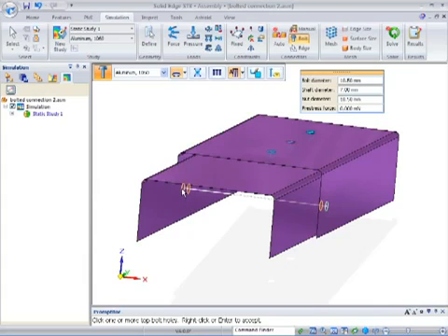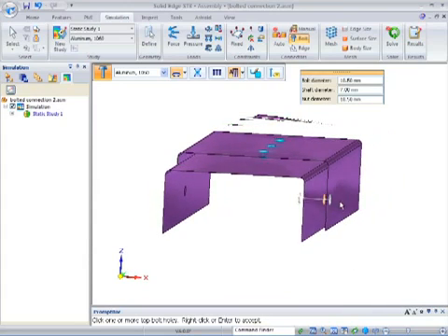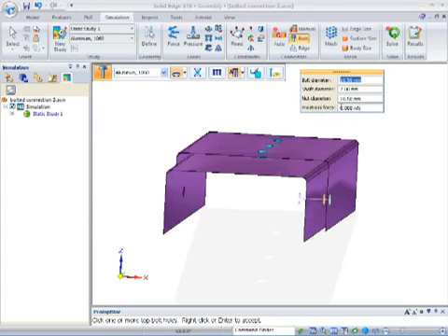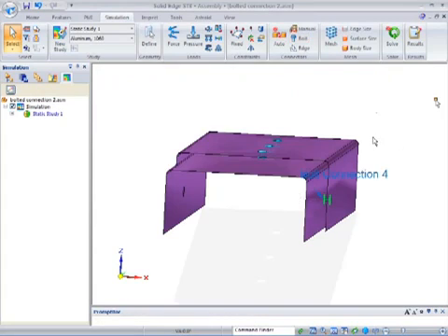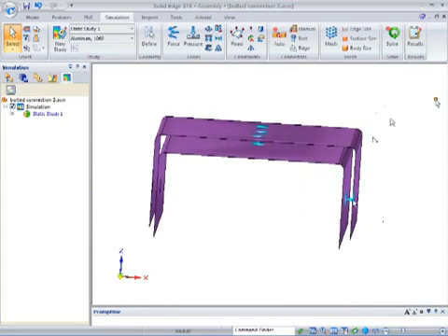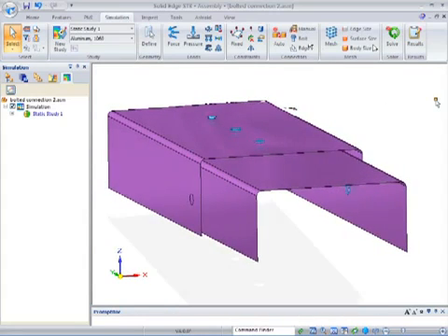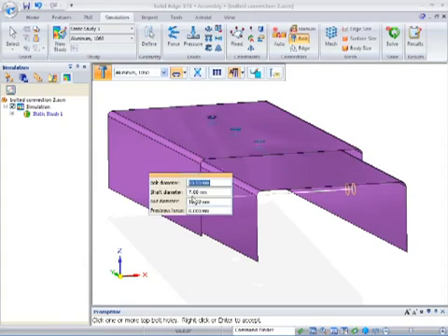So all you have to do is come to the end and grab that sphere and just simply drag it back and change the search value to from the top to the bottom here. Key in our pre-stress value again of 100 millinewtons, right mouse button click, and it creates that bolted connection for the right side. The only thing that's left to do is create the bolted connection on the opposite side.